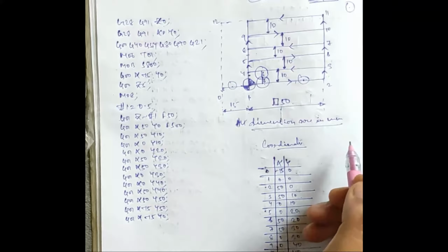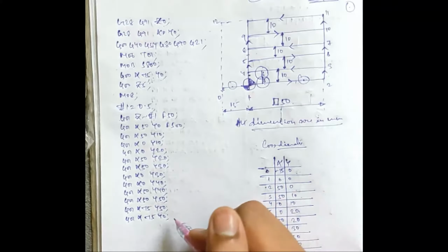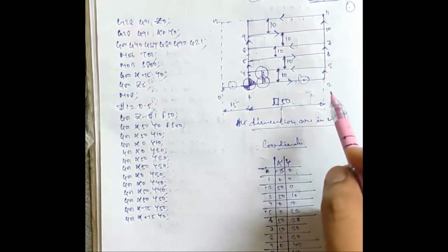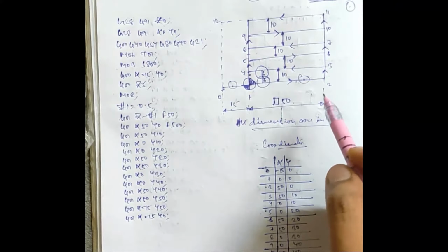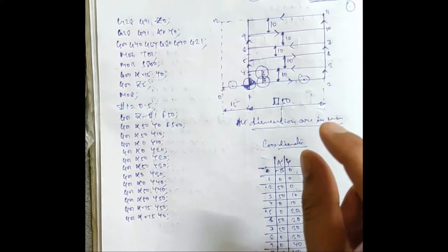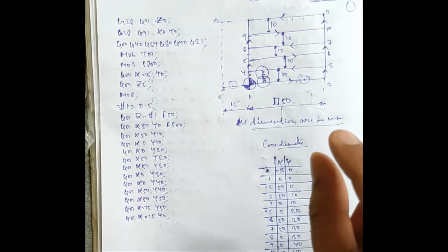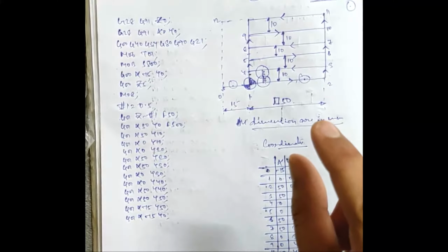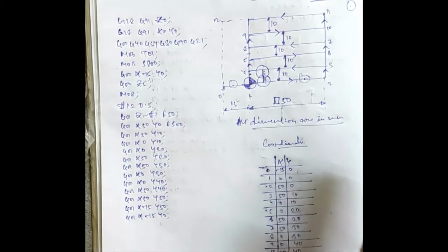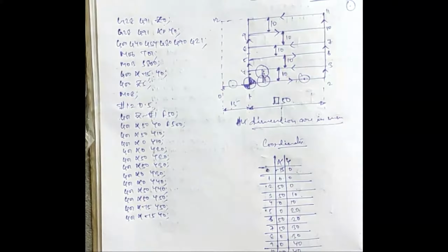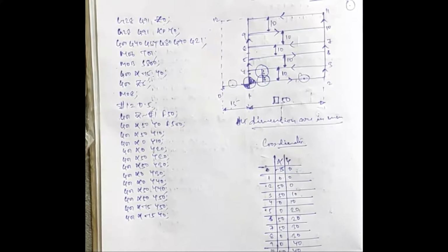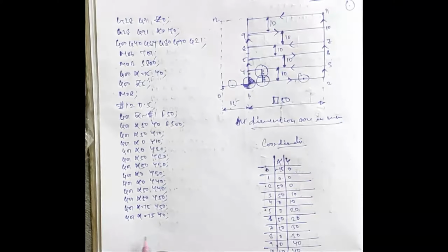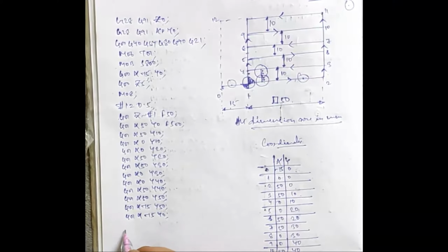Okay, so there is something over here. Then there will be a question in your mind: while doing facing, up to what extent, up to how many mm are we going to remove the material by the facing operation? Let's say about 5 mm. Okay, we have to remove 5 mm of material from top to bottom by the facing operation. Clear?